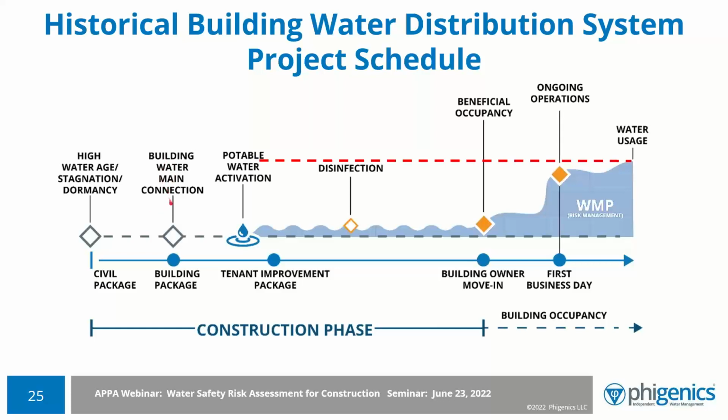The building gets built, shell and core. And at some point, the contractor, for their convenience, says that they're going to activate the water system, not because the owner needs to use it, it's because they're going to use it for either contractor bathrooms or for materials assembly. I call it adhesive and muds, to mix something that needs to be used in the building. So they just fill up the water system as they complete it, and they move on to their tenant improvements. No one manages the water. They just draw a small, tiny amount of water off of this system, but they fill it to its capacity, and they only use this tiny amount. Meanwhile, all of the other water is in a highly aged state.